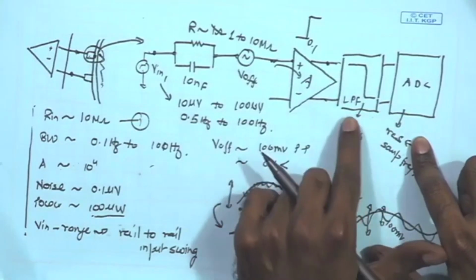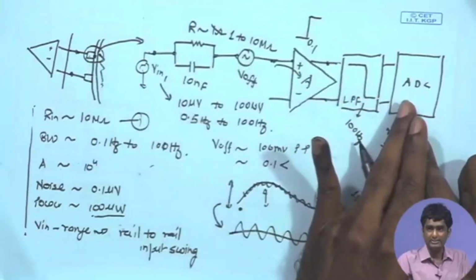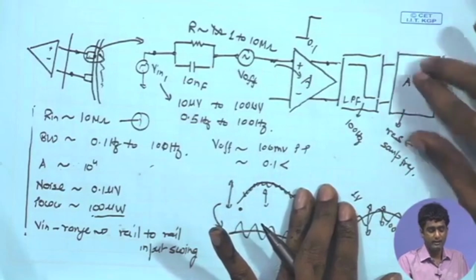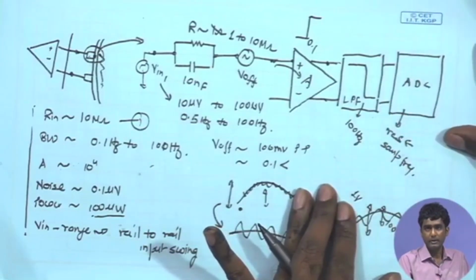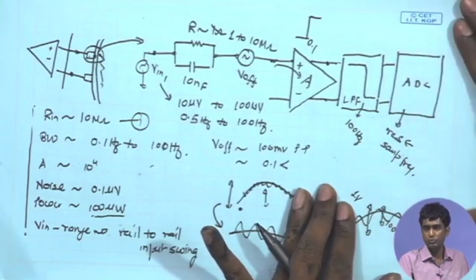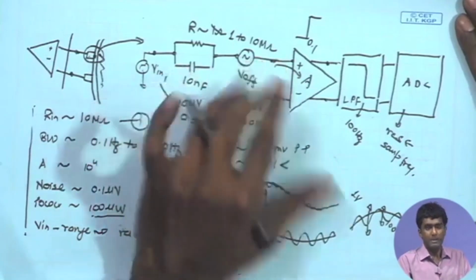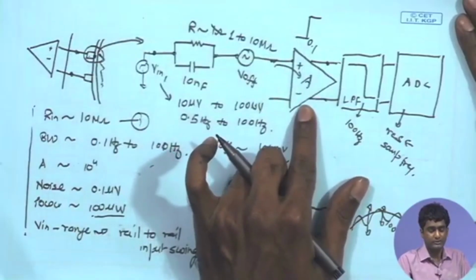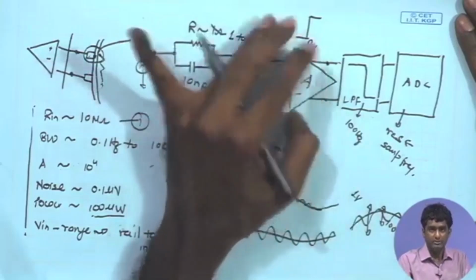As a result, I would like to maintain the fully differential operation even till the last stage, so that even the ADC can be operated in a fully differential mode, and finally, the digitized signal enters into the DSP or digital signal processing domain, which is immune to those kinds of noises. So, even though the input, for example, may not have such large common mode noise sources, the VDD noise is maybe the only noise of concern for the input stage.